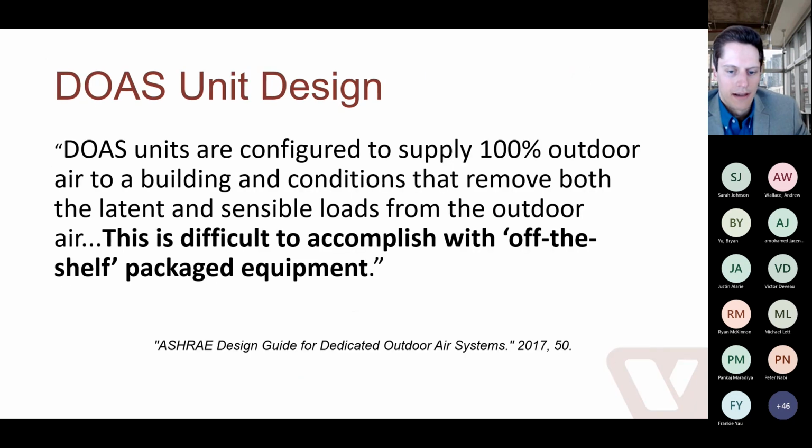I pulled this from the ASHRAE design guide, but essentially it says that handling outside air up to 100% is very difficult to accomplish with off-the-shelf package equipment. And I might be so bold as to say it's hardly possible to do that. ASHRAE is a little nicer to the package rooftop units than I would be, but ASHRAE is certainly on board with this notion that we need to do things a little bit differently for a DOAS unit than we would for a package rooftop unit.